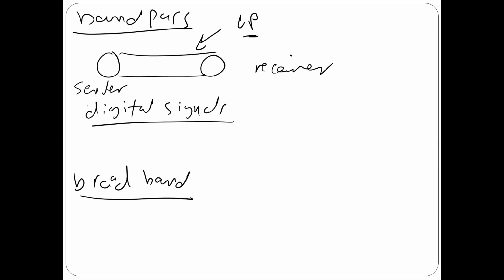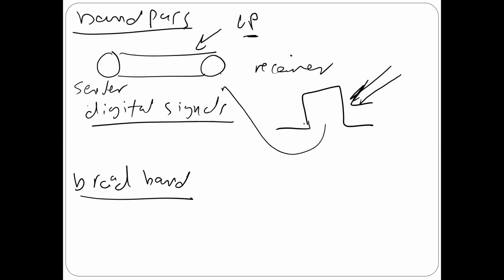And also, and this is the most important thing, I told you also only one can transmit. Okay, so you actually use the whole channel. You got what I'm saying? So it's not allowed to have multiple transmissions here because you are going to use the whole bandwidth. I told you the reason I have to use the whole bandwidth is that if you have a square wave like this one, it actually has infinite, too many frequencies. So if I give you a small amount of frequencies, you cannot transmit this one. Very simple. So that's why here I have to use the whole bandwidth.